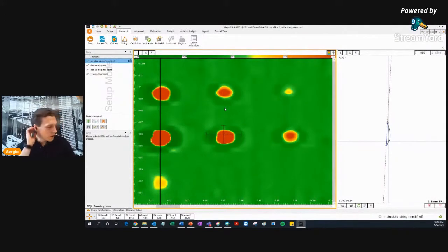And just please don't forget, with pancake eddy currents or with an iFlex probe, it's more of an approximation. We cannot call it sizing because it always depends on how many points we have on our sizing curve. And if you just have like 2 example points, then the curve would just be one straight line. It might not be super accurate all the time. So it's more an estimation. And then also one scan to another can vary a bit, and then also where you place your cursor.